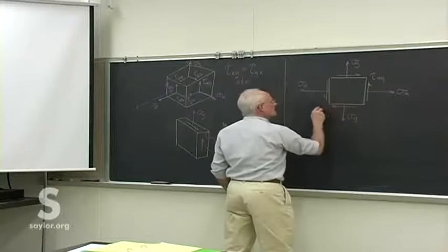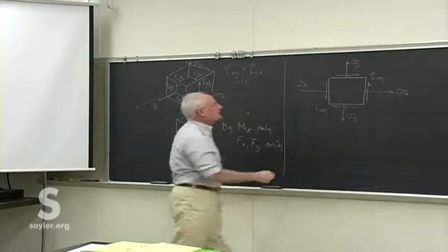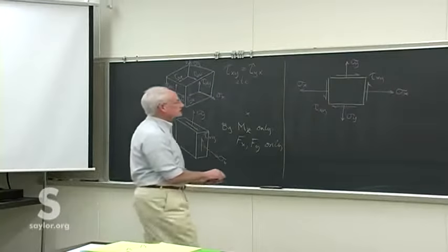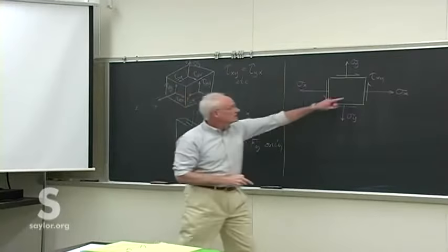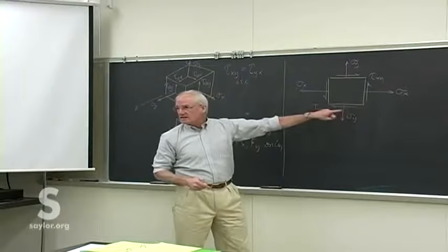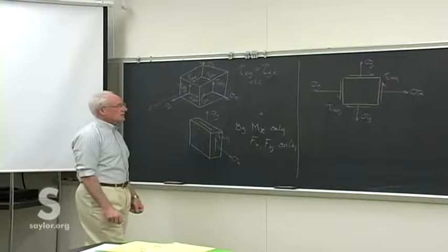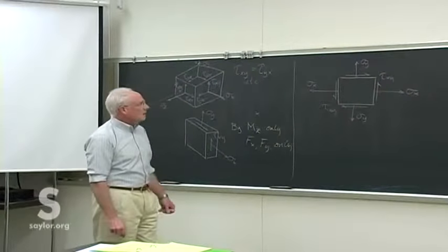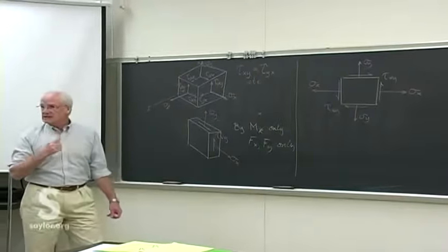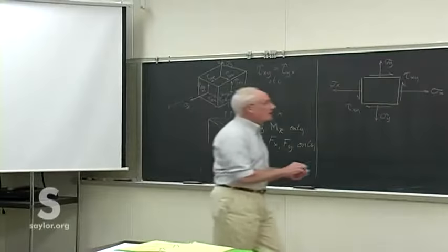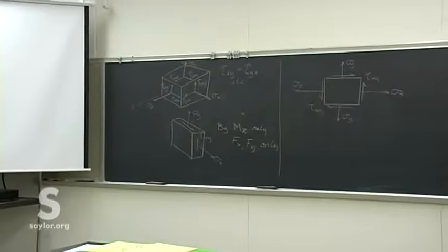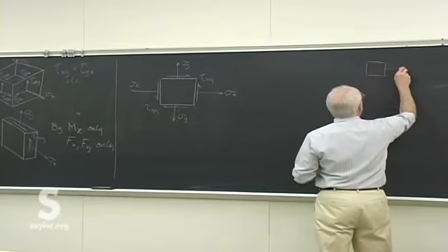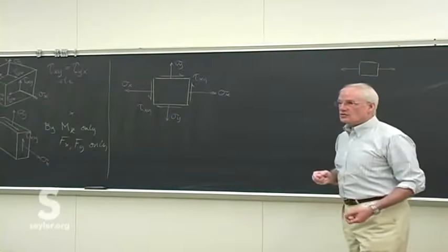And then the shear stresses across the face. In fact, as often as not, we won't even add that xy, because all of those, remember, these four shear stresses on the faces are all the same, as they must be for a moment and force balance. What we're going to do now, and we touched on this actually several weeks ago. We did it when we were only looking at tension. We did it was something like the third week or so, where we took just the axial loads that we were looking at that time.